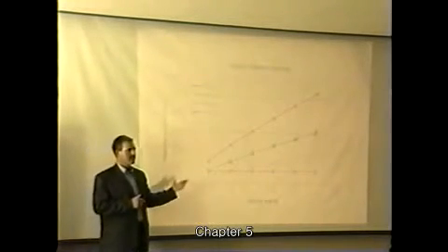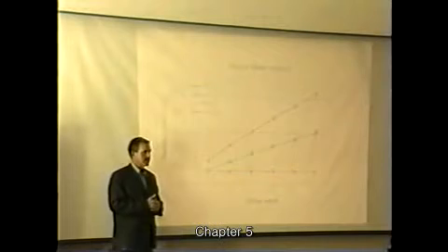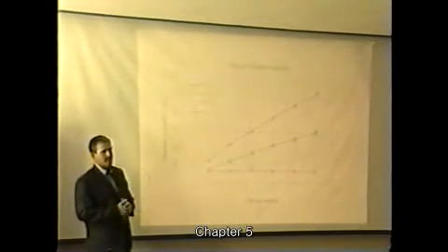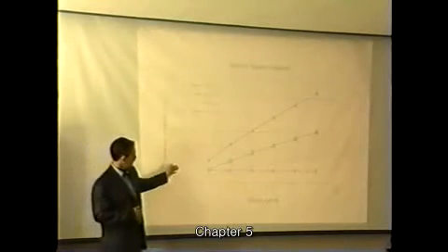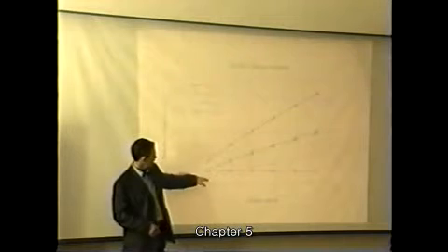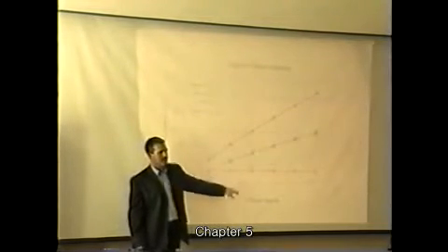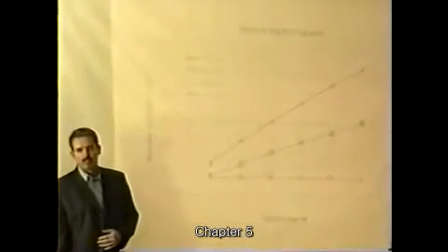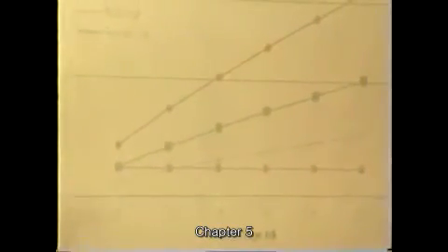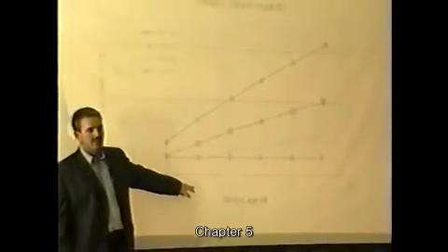So if you want any nitrification to happen, you would be required to run extremely high mixed liquor concentrations. As you can see, to get underneath this straight line, you need to run at about 6,500 mixed liquor total solids concentration. But that will give you only a 10-day sludge age.